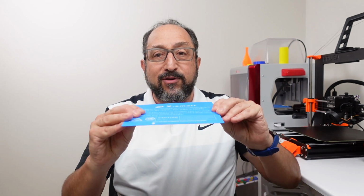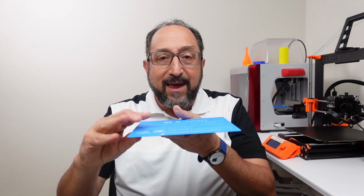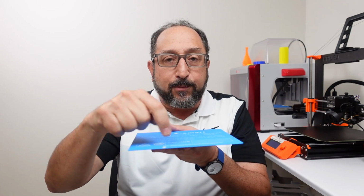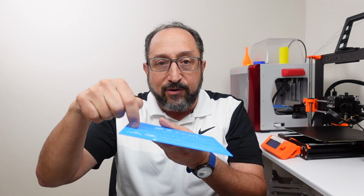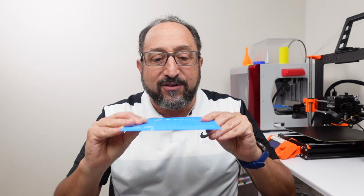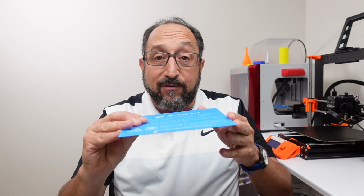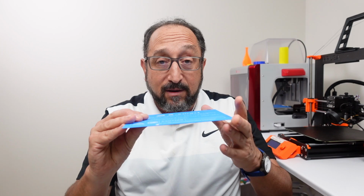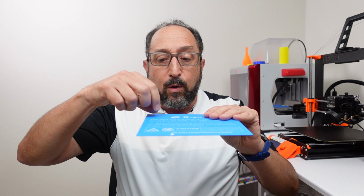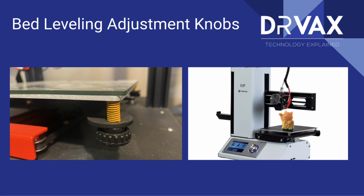In order to produce a successful 3D print, you need your print surface to be level. It has to be the same distance between the nozzle and the print surface everywhere it's printing. If it's on an angle, it will be closer here and further here. So it has to be as level as possible. The way you manually level this print surface is by adjusting knobs generally underneath or little screws on the top. The bigger the knobs, the easier it is to adjust.